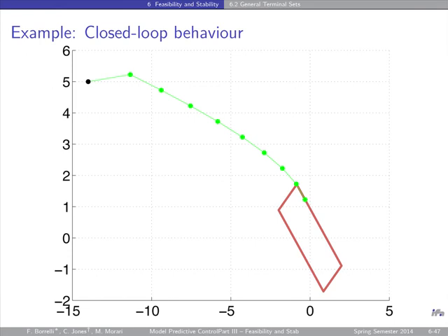Okay? What is interesting about this? That there is no model mismatch. You apply U1. Where are you going to be at the next time step? You're going to be here, right? As you have predicted, because there is no model mismatch. Okay? From here, you run MPC. And what is the optimal input sequence? Well, this is the optimal input sequence. I'm going to flip between the first and the second one. So you see that we are not using LQR.